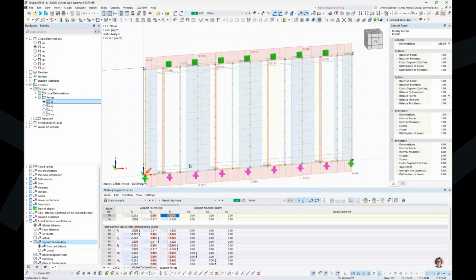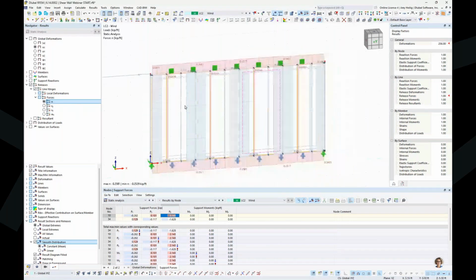And also remember, the sheathing panels themselves are not one continuous sheathing, but they are in those 4-foot increments all modeled here. So all of these come into play with true FEA. So that's why we might see slightly different forces here for our shear force, versus something like hand calculations.